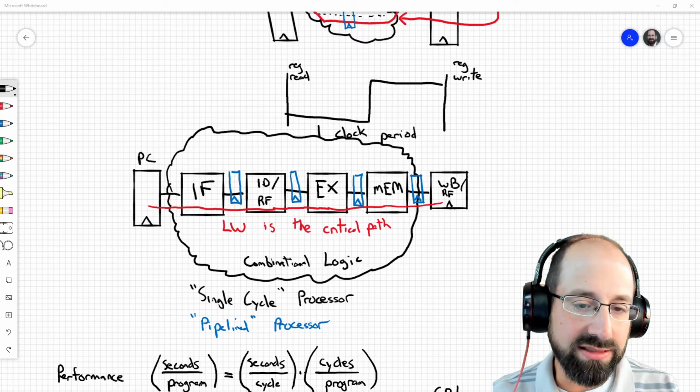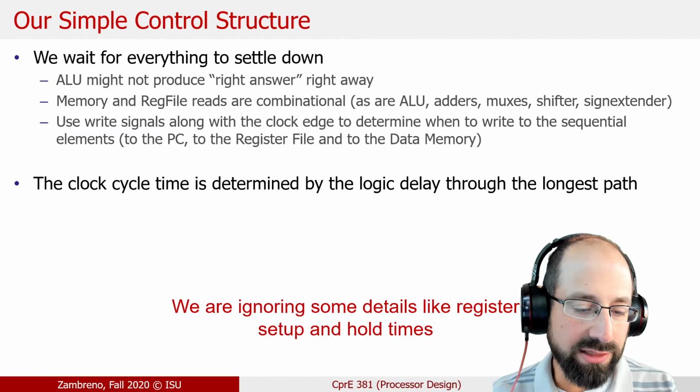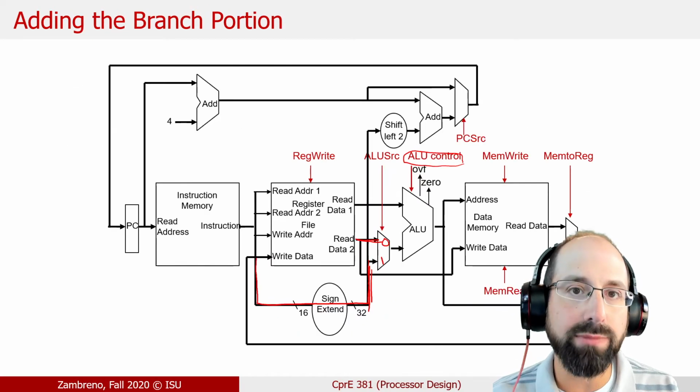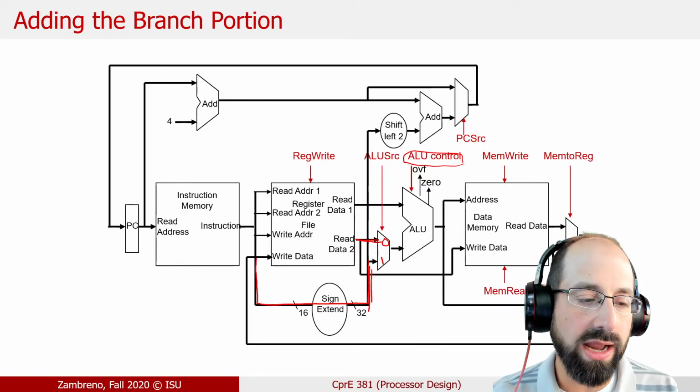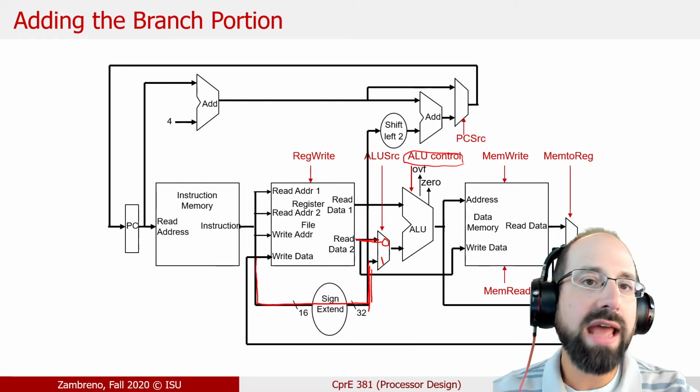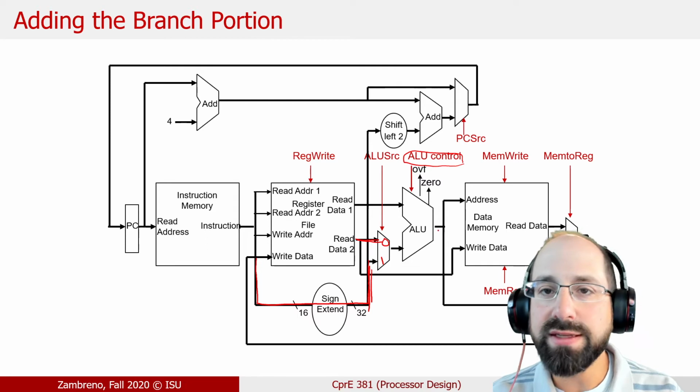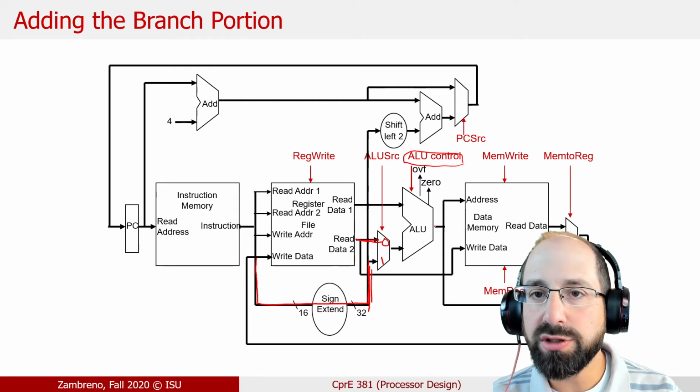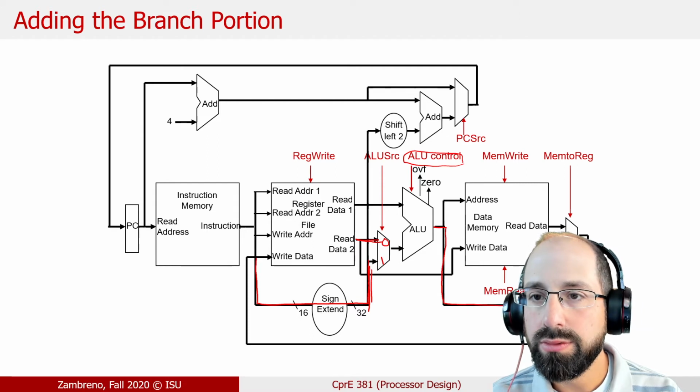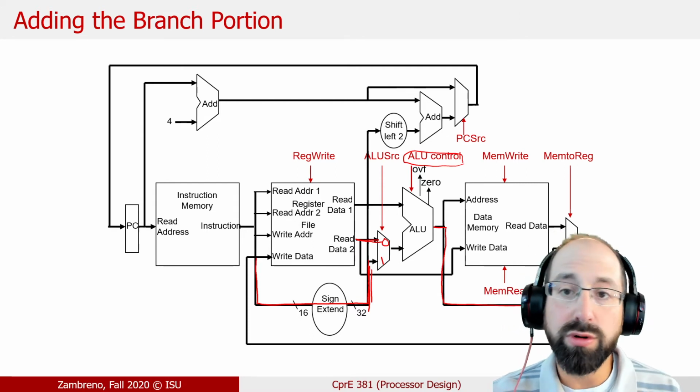And in terms of what our design winds up looking like, as we kind of trace our way through this diagram for an add instruction versus for a load word instruction, for the add instruction, we have this memory happening here. But in terms of the critical path we could analyze for that instruction, we're avoiding it entirely, right?